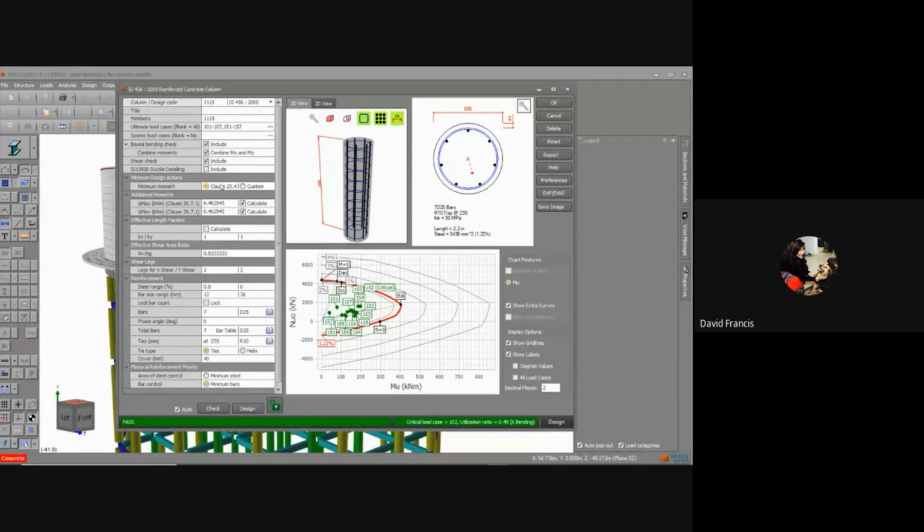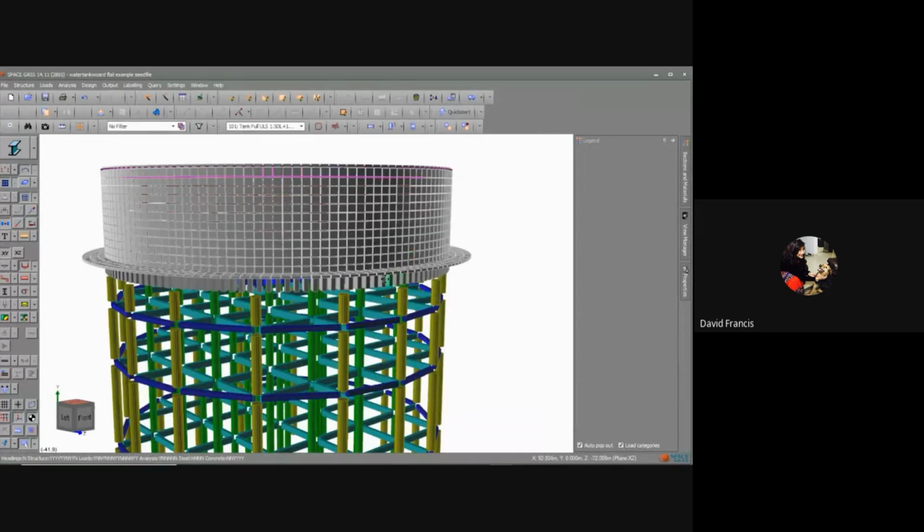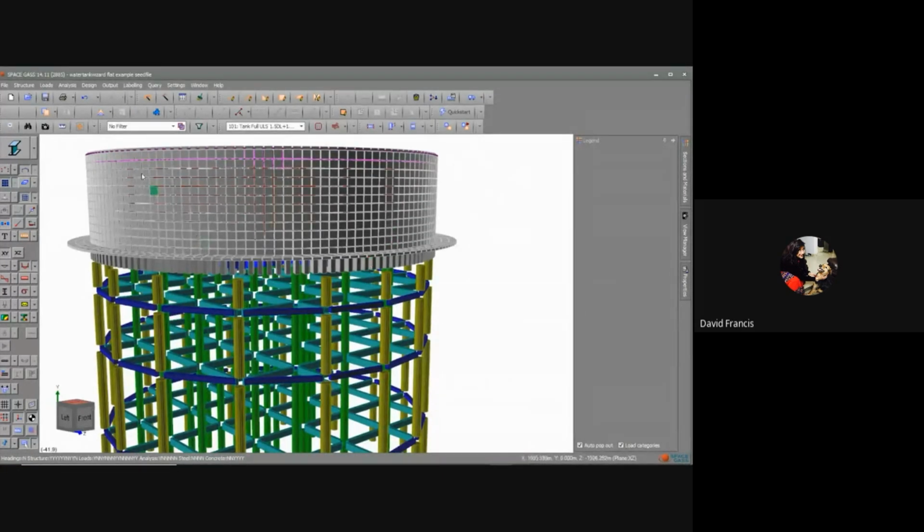Of course, this is all to IS456, and it includes 13920. Being a column, it won't include the allowance for crack control because cracks are not considered for the columns. But I can include 13920, and it will then go into redesign mode and update mode, and so on. So I go out of here. If I just want to be outlandish, I can just take the ring beam.